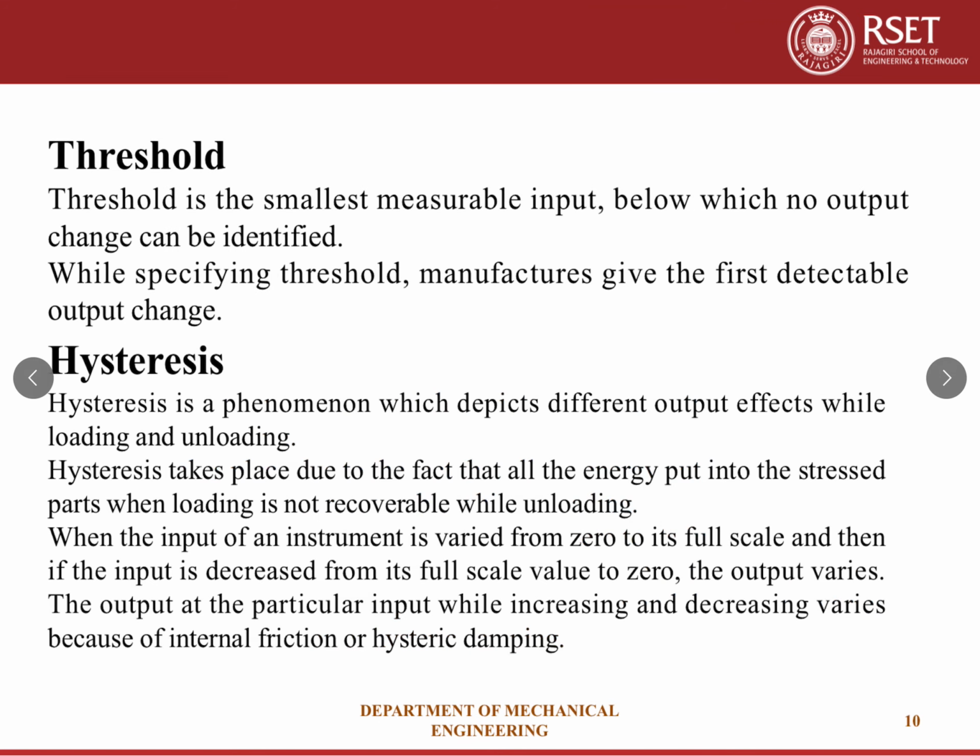Now threshold. Threshold is the smallest measurable input, below which no output change can be identified. That is, when we start reading from zero, the point up to which there is no output variation is called threshold. It can be defined as: if the instrument input is increased very gradually from zero, there will be a minimum value required to give a detectable output change.